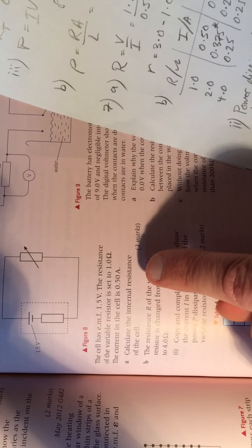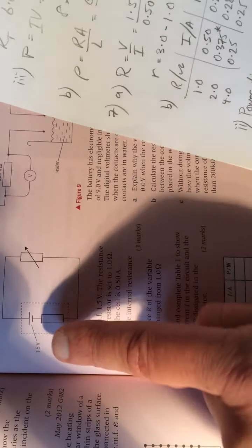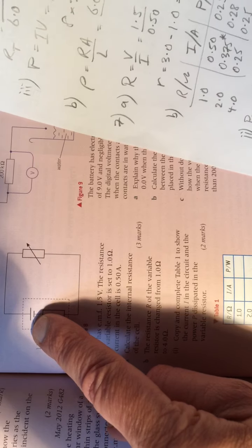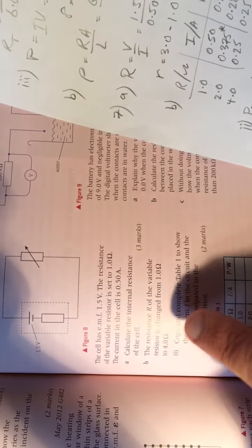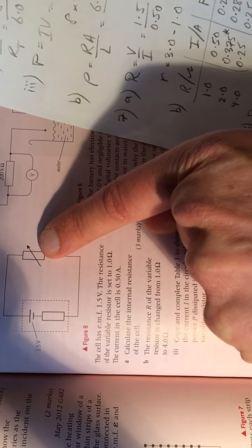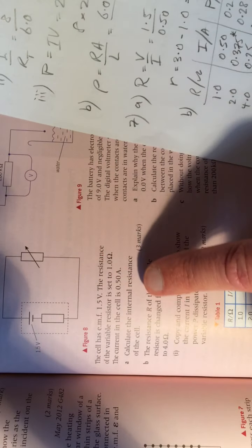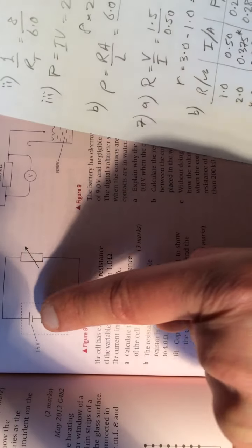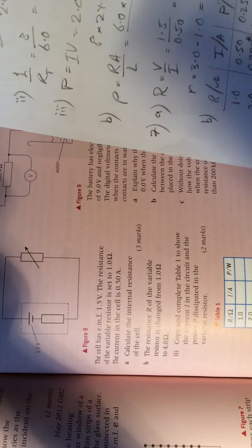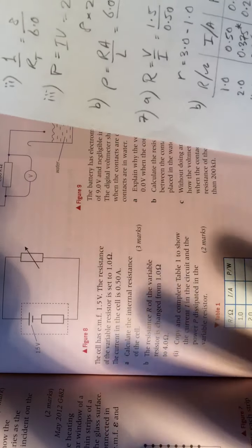And that can only then be the internal resistance, because there's 2 resistors in the circuit. The internal resistance, that is the resistance of the cell, and the external resistance, the resistance of the variable resistor. So that if we get the circuit resistance and take away the resistor we know, we'll get the unknown resistor, right? It doesn't matter that it's internal resistance, it still works in the same way.